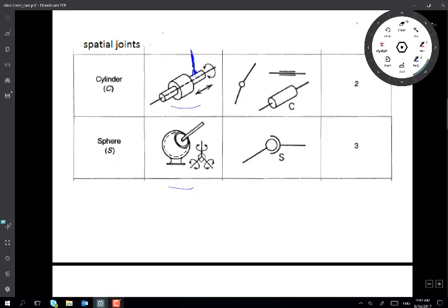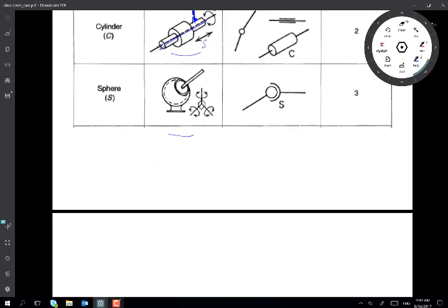The cylindrical joint allows the link to slide up and down inside, but also allows the link to rotate. Sliding remains in a specific plane, but once it rotates with an angle theta, then it comes out of a plane. Hence the cylindrical joint is more of a spatial type joint. The other joint which is used more in spatial linkages is the spherical joint. We also call this the ball and socket joint, right? That's another name.